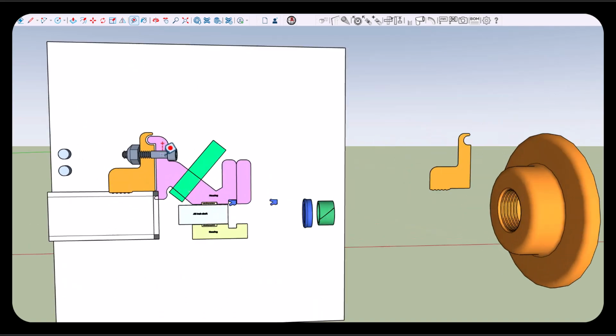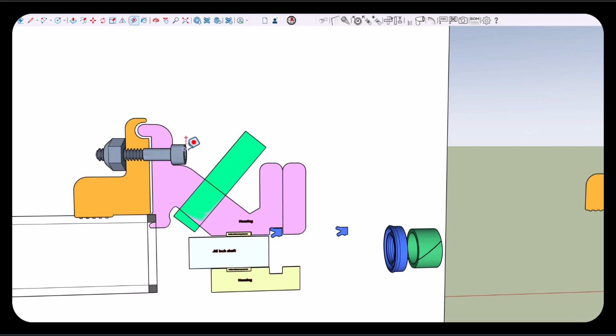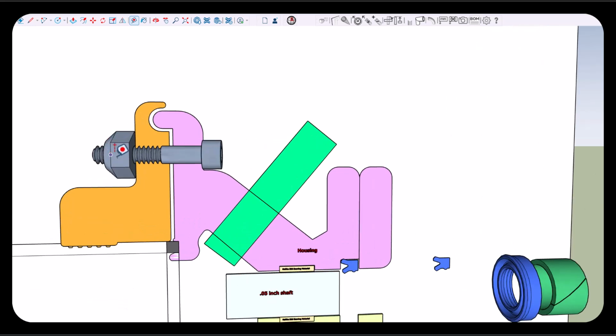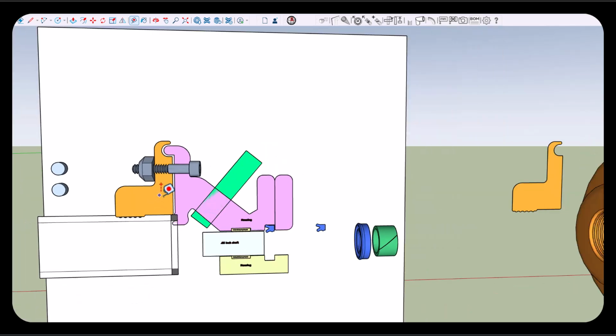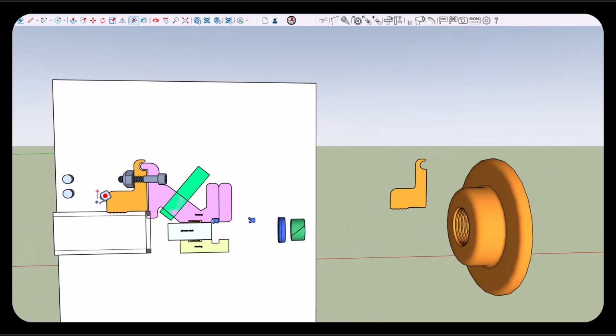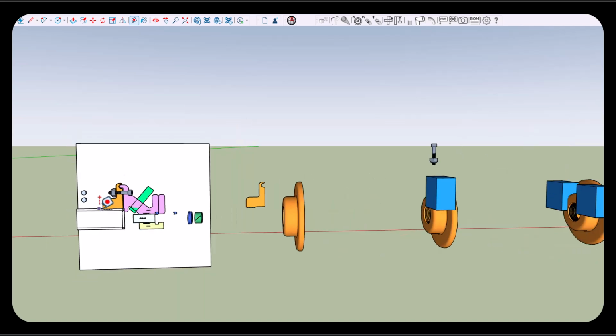And this is a 10-24 socket head bolt with a nylon insert locking nut, and these bolts will be made of brass, and this nut will be made of stainless steel. I don't want to use stainless steel on stainless steel because it galls and it'll lock it up. These metals are all brass. I think the red brass. I put them in different colors so you can keep up with what's going on.